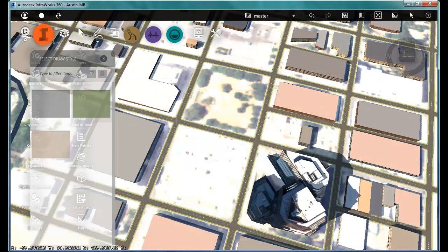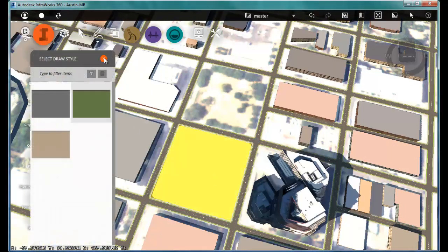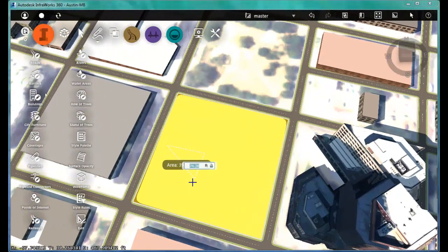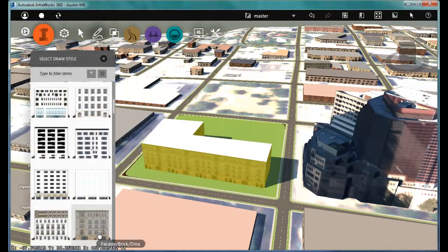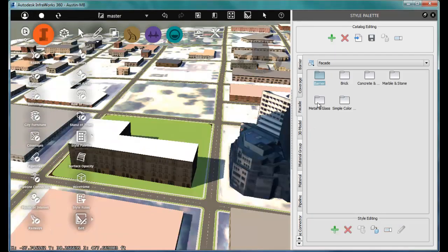First, let's cover up the parking lot since we're going to be looking for a more green solution. Now I can begin massing in a simple office building, picking points to lay out sort of an L shape. And once I'm done, I can modify the shape, change the fascia, I can add some slope to the roof, whatever I feel like doing to tweak that design.